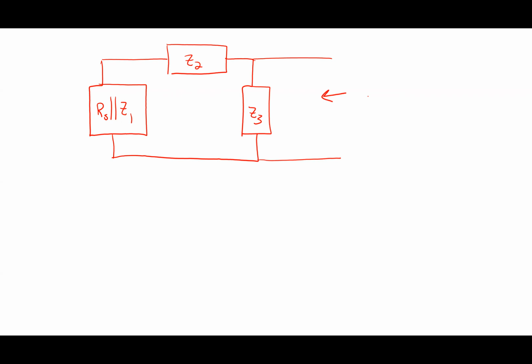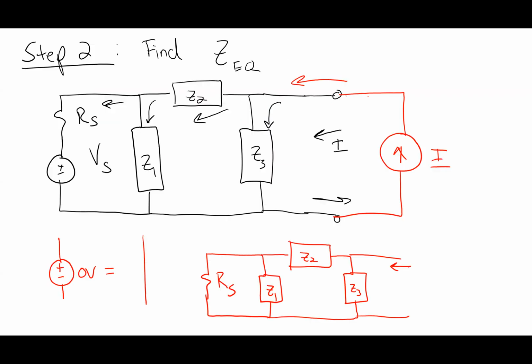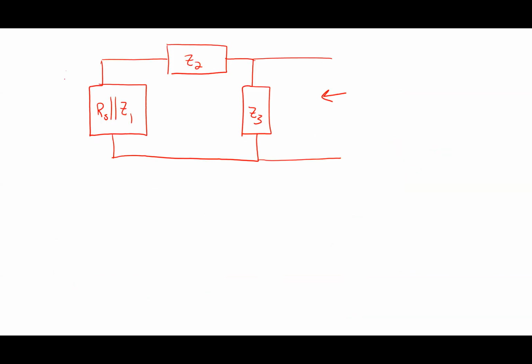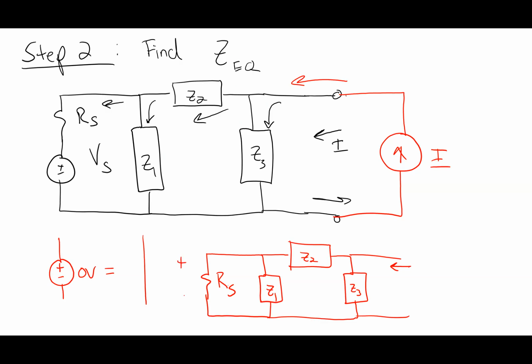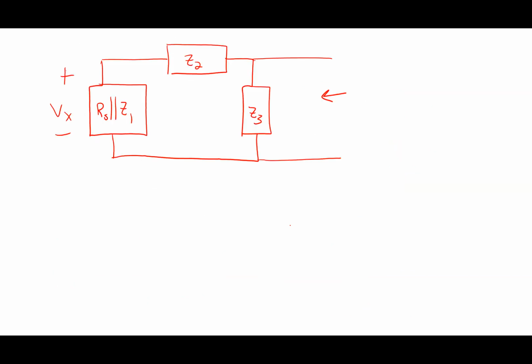The idea is that everything about this circuit and this circuit is equivalent. They're equivalent circuits. In other words, the voltage across Z1 is the same as the voltage here. So if I called this Vx, and I called this Vx, the currents and voltages everywhere in this network are the same as they are everywhere in this network. They're equivalent circuits. That's the way of thinking of it. What's the next simplification I can do? Again, thinking backwards. You can do what?